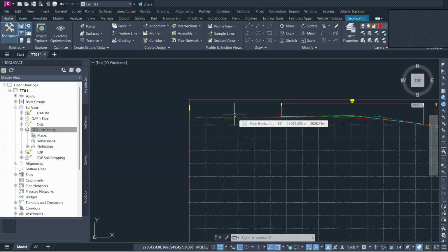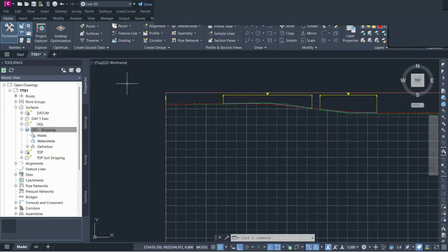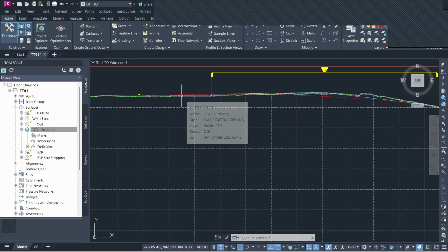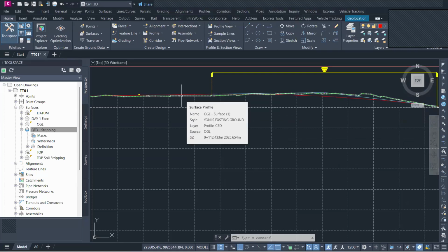The first scenario is an instance where you're going to import or fill, bringing in new sub-base and base material. For example, you need a quarry so that you can bring neat gravel that meets the minimum CBR requirements for you to construct your sub-base layer.